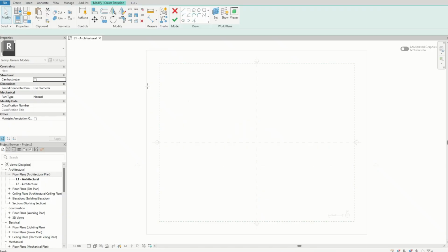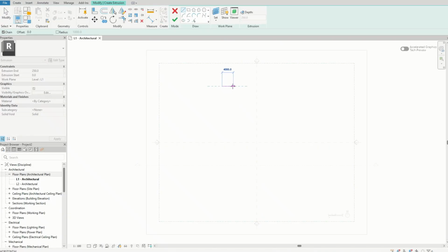Step 6 to 7. Create the extrusion profile. From Forms, click Extrusion. Use the Draw tools to sketch a closed-loop profile. The shape is not important here. Keep it simple. Multiple boundaries are allowed. You can also nest a boundary inside another to create a cutout, as long as boundaries don't touch.